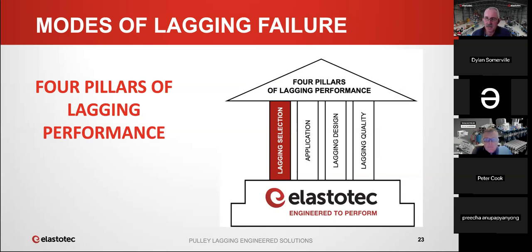Some people consider lagging as a consumable that is just used up and regularly replaced. We consider it to be an engineered part of the pulley, just like the bearings, locking elements, shaft, etc. And if it's selected properly, applied properly, designed properly, and the quality is correct, with the exception of the high tension bend pulleys, it should last as long as the mechanical components.